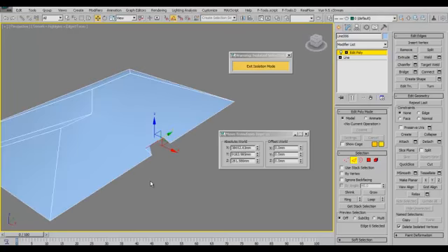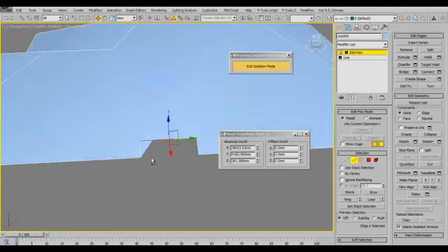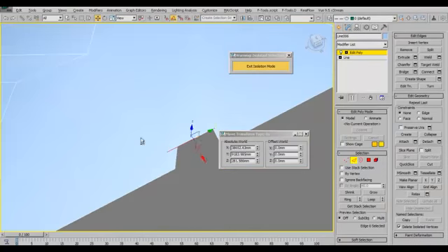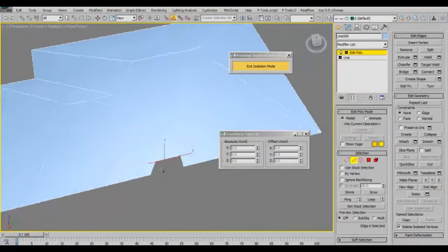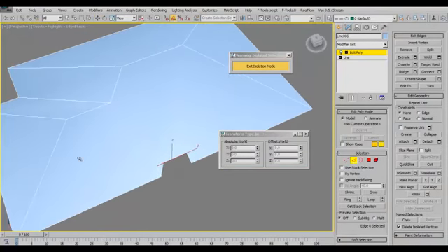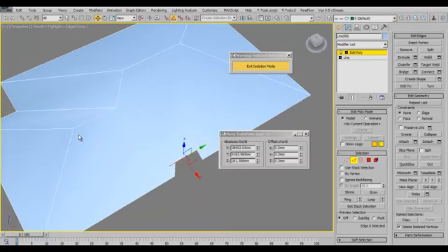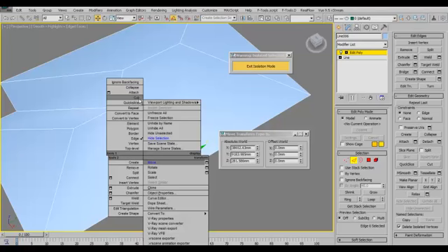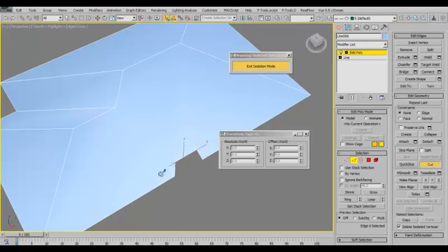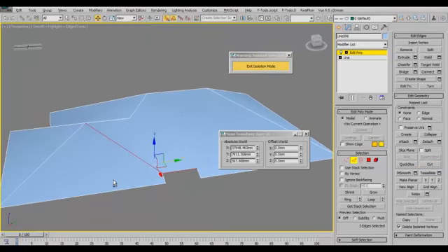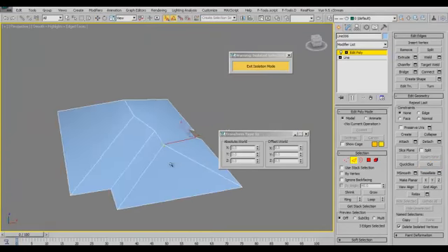And that little error we have from our lapping mesh is because the mesh is not really understanding what is happening here, so it's covering up and lapping it over here. So what we need to do is just cut an edge from here down to this point, so it actually covers that area up. So we turn on the snap and we cut through this area, and it fixes that error. And I think we have our roof.